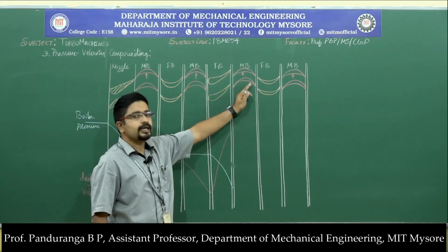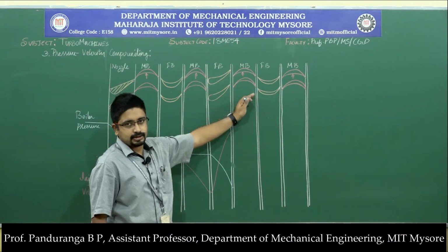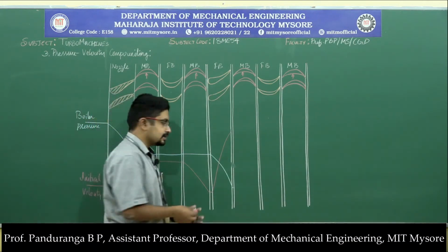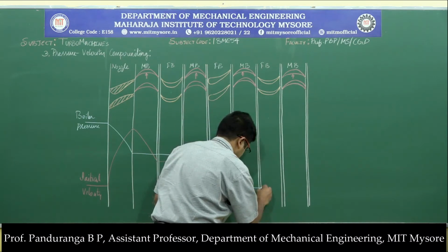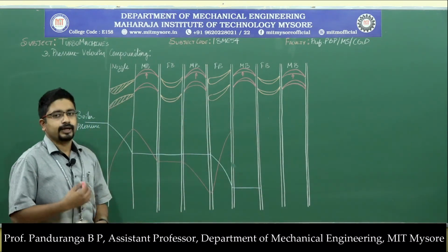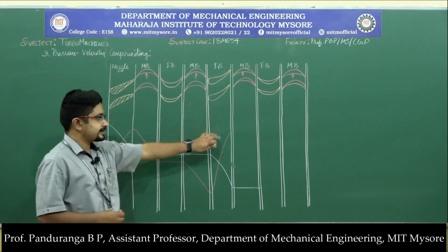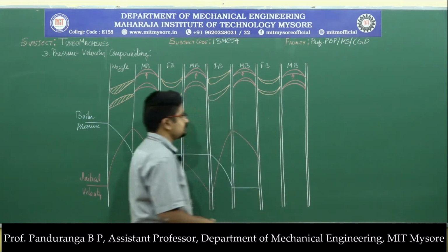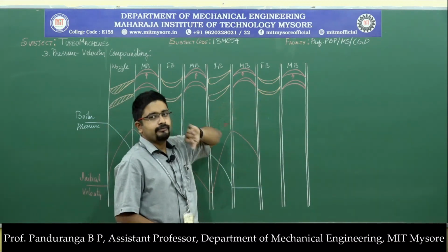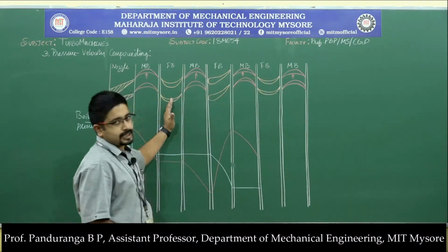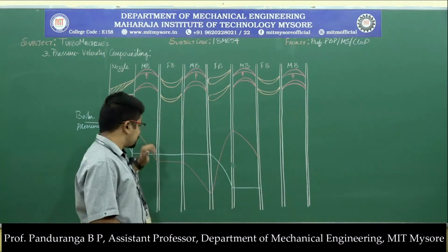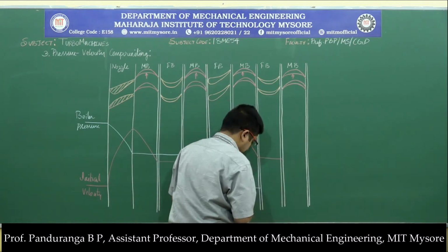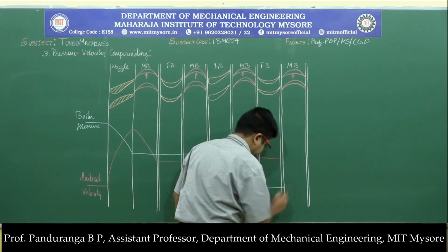Now the steam passes through the moving blade. So the moving blade is symmetric in structure, beta 1 and beta 2 are the same. So because of that there is no change in pressure energy, so the pressure remains constant, but the blade absorbs a certain amount of kinetic energy from the steam. So because of that the velocity reduces. Now the steam enters the fixed blade. Here it is symmetric, similar to the second row of fixed blade. So because of that there will be no change in the pressure and kinetic energy or the velocity. So the velocity remains constant and the pressure also remains constant.